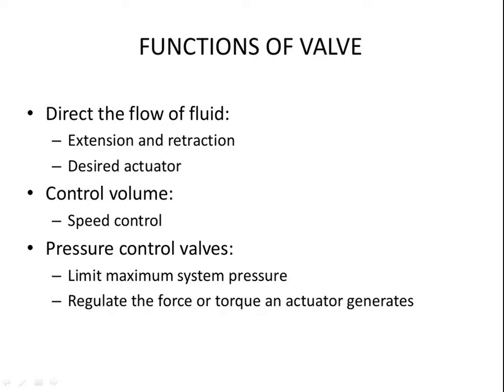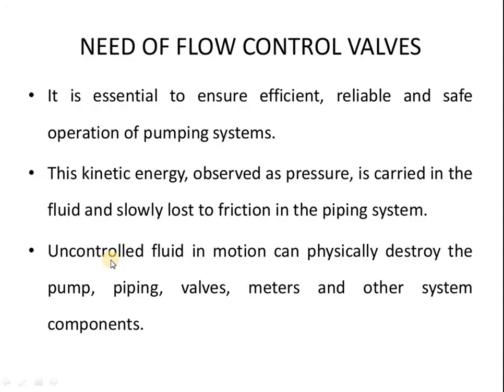First, direction control valves control the direction of the fluid flow in the system, that is air flow in the pneumatic system, directing the flow of fluid for the extension and retraction stroke of the desired actuator. Flow control valves control speed, and pressure control valves limit maximum system pressure and regulate the force or torque an actuator generates.